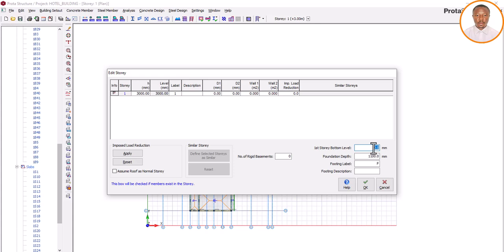After digging, once you have finished digging and you are laying your blocks, your block will reach the surface of the soil, isn't it? Then from the surface of the soil, above the surface of the soil, to the point where you have your plinth or oversight concrete. Since it's public, it says 600, isn't it? We say it's 600.